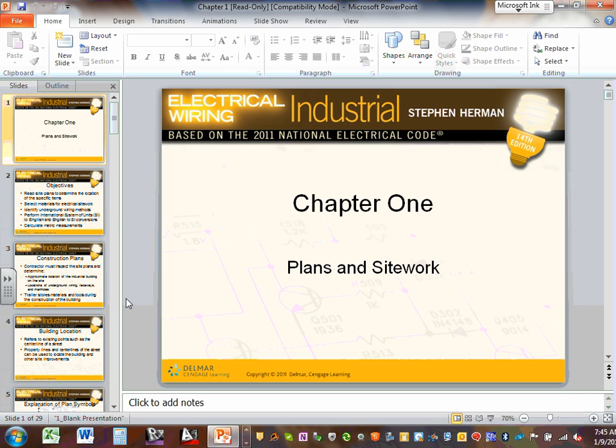Then you come over here, and that's how the power is coming to this building. So they're bringing a 1500 amp fused disconnect, a 1600 amp fused disconnect and a 1000 amp fused disconnect. They're coming into this building to feed the whole building through a couple of buses, plug-in busways, and a couple of panels. And I'll go over this one in detail when we reach it. There's a chapter talking about each one of these aspects. Did you guys hear me? So this book, 20 chapters, each chapter takes one segment of this project and talks about it, exactly like the commercial project did.